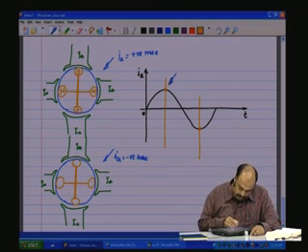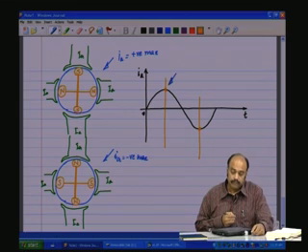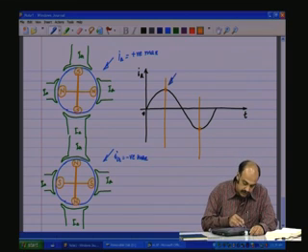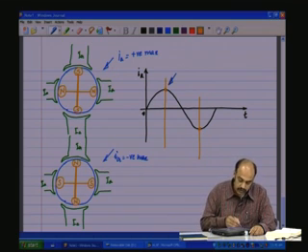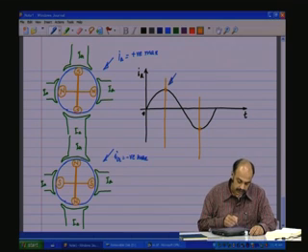See the north and the south. So south becomes this and this becomes north. Which means there is a movement between this and this. It looks as though the MMF has rotated by 90 degrees. Between this and this, the MMF has rotated by 90 degrees mechanical.